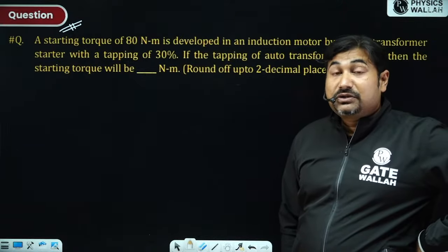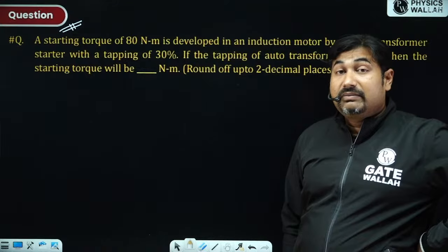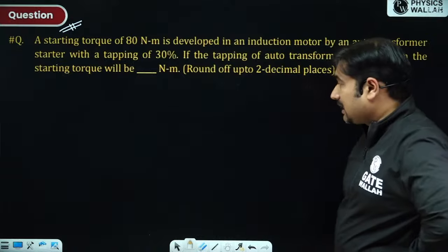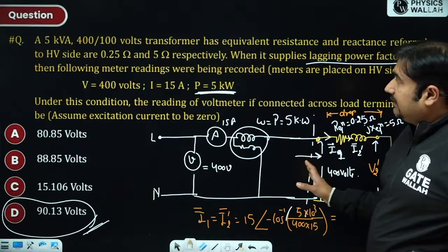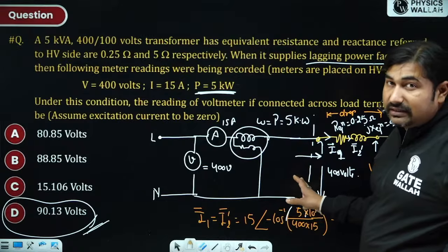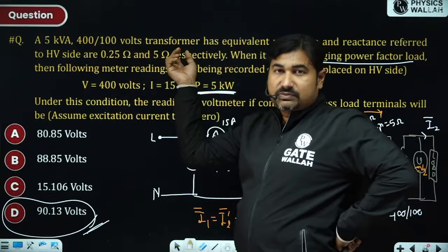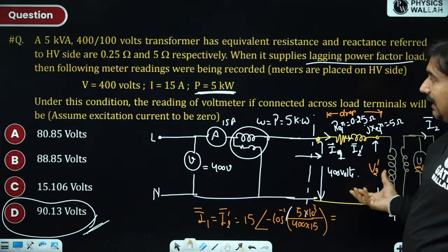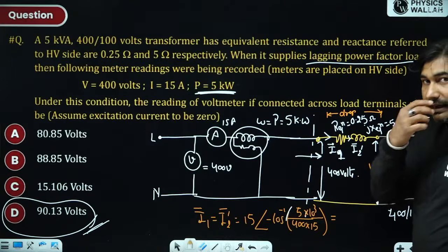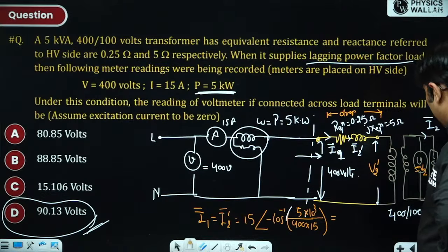But you must remember the loading factor, because your transformer secondary side is not on full load. So that needs to be considered here. If you are going with R per unit, X per unit, then the loading factor, full load current, and under this condition what would be the current I2 dash, the difference of that needs to be considered well.